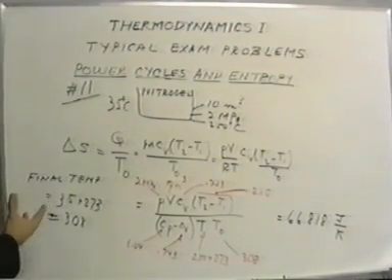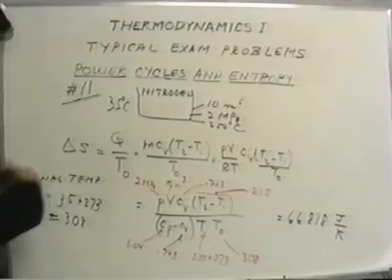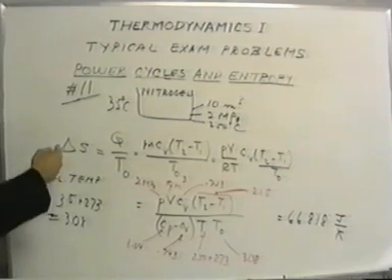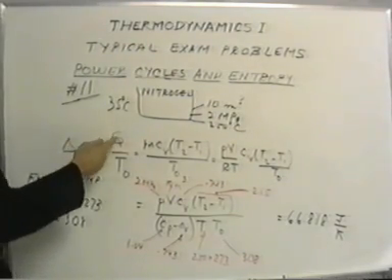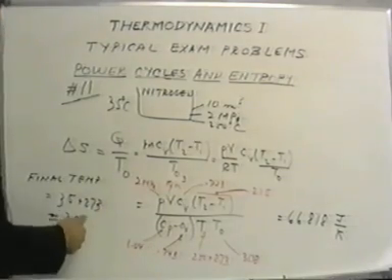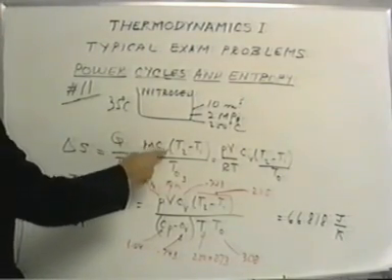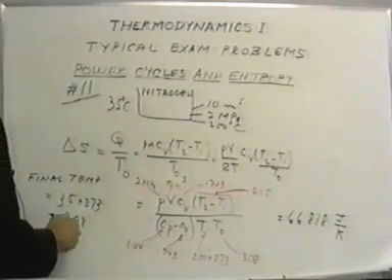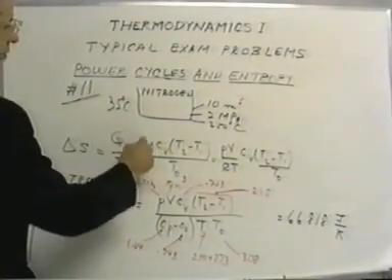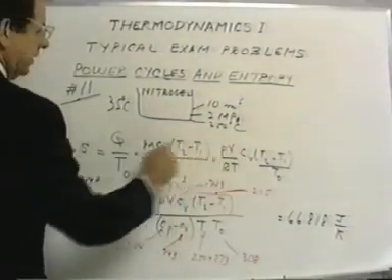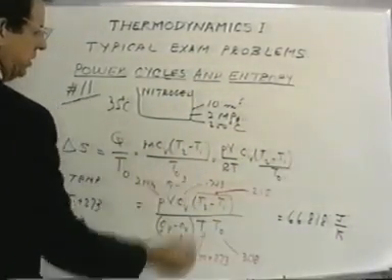Well, after a long period of time, the temperature and everything will settle down to be 35 degrees, so the final temperature will be 308 K. Now, the change in entropy is given by the ratio of Q over T0, where T0 is the 308, but Q is equal to m c sub V times the difference between T2 and T1. Now, m in turn can be replaced by PV over RT. There's a C sub V again, T2 minus T1 over T0.